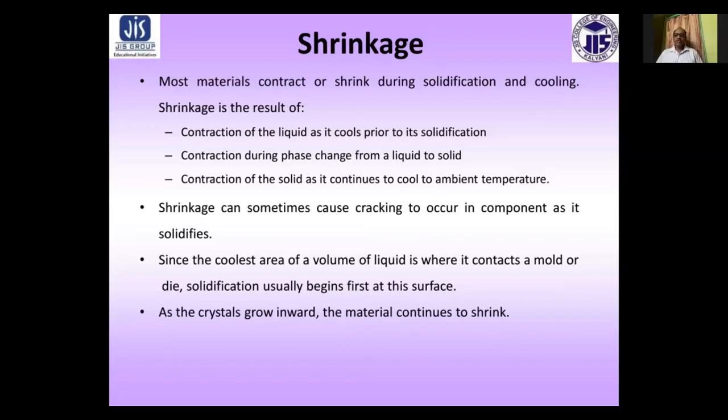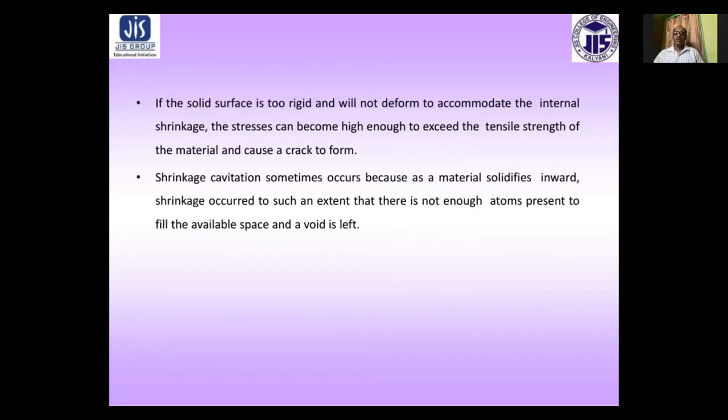As the crystal grows inwards, the material continues to shrink. If the solid surface is too rigid and will not deform to accommodate the internal shrinkage, the stresses can become high enough to exceed the tensile strength of the material and cause a crack to form.